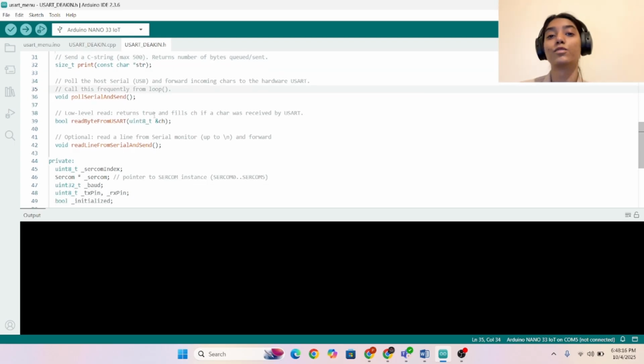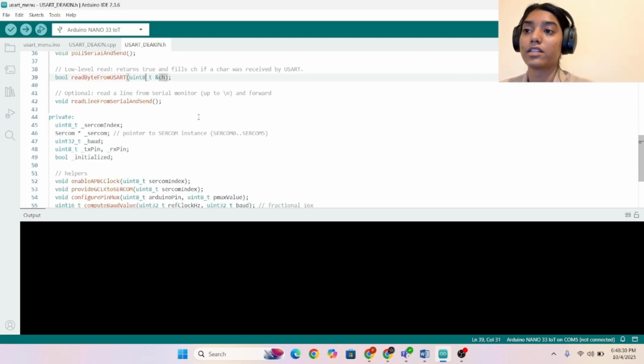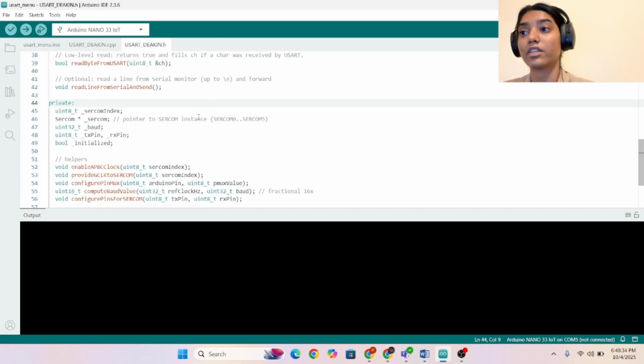Then here we would be using polling because we want to keep on checking, instead of having any sort of delay when an interrupt happens and having a debounce value. We would just be using polling for this case. If a person ends up writing something onto the serial monitor, and the delay is pretty small, we can immediately act upon it.